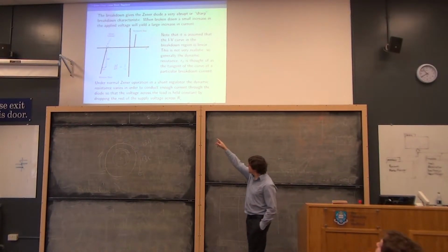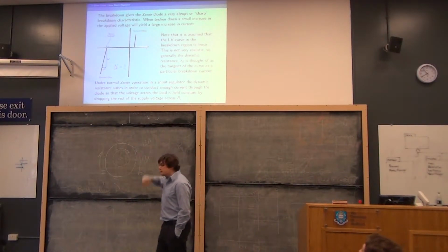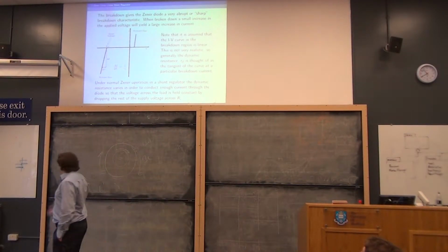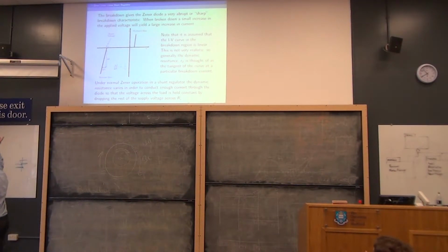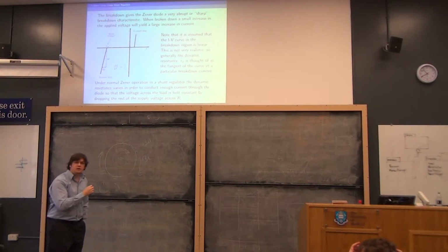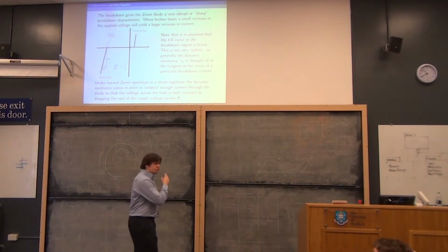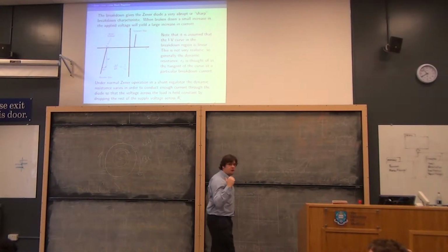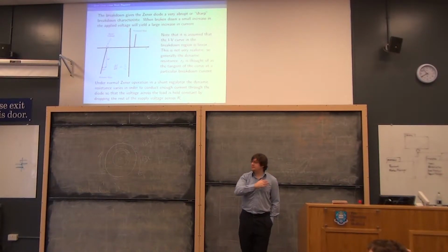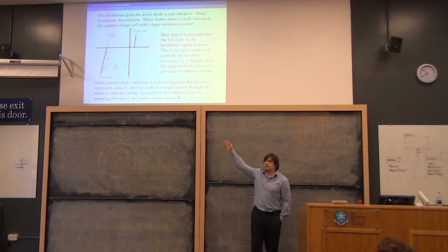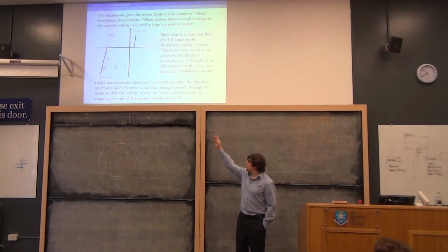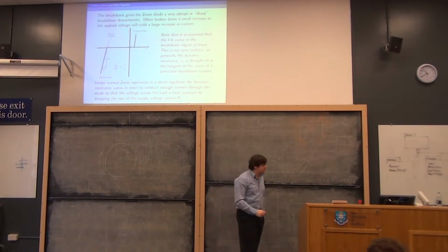So we were living somewhere in the slopey bit on the left, say in the middle, just next to where the delta is for delta I. If we were there before and we adjusted the cathode to anode voltage across the Zener diode, slightly making it smaller, the current will have to drop a bit, and because we're stuck on the line, we cannot just wander off the line. We must have moved upwards slightly. So voltage has dropped a bit, and the current's dropped as well.